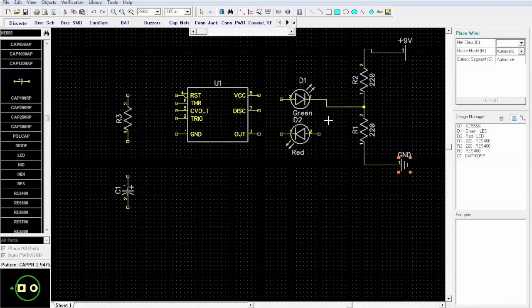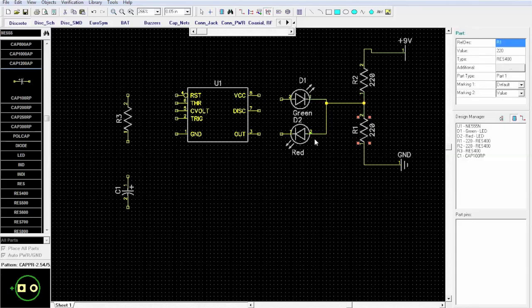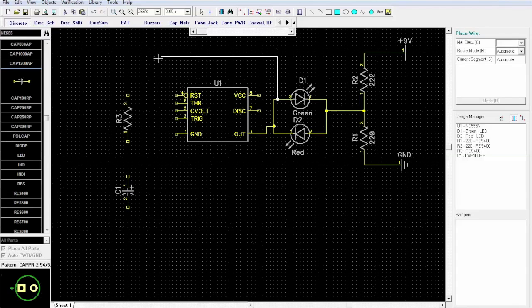connect it that way. Control Z if you make a mistake, or click on the wire itself where you want it and slide it. You can go back into default mode and you can adjust where the wire sits. So if you like the symmetrical appeal, then that's the way to do it. If you want to get an angle, you can click and start going down rather than waiting for the automatic to go through and make the adjustment for you.